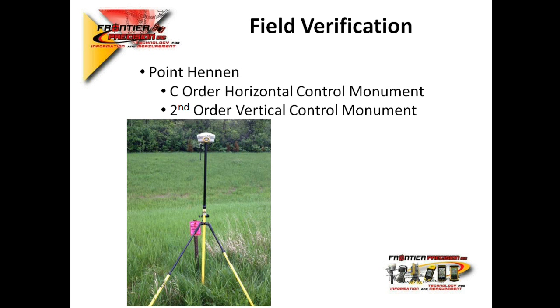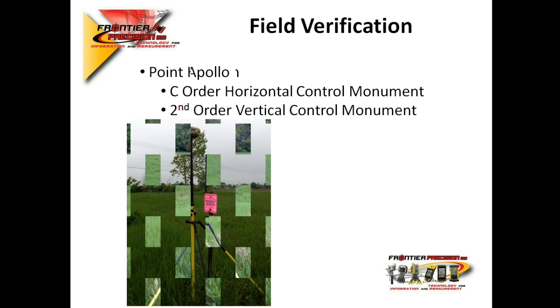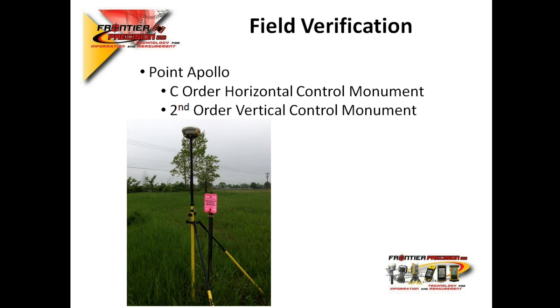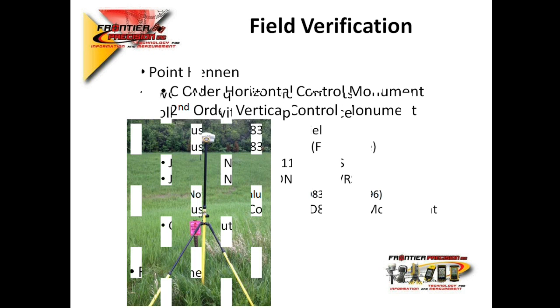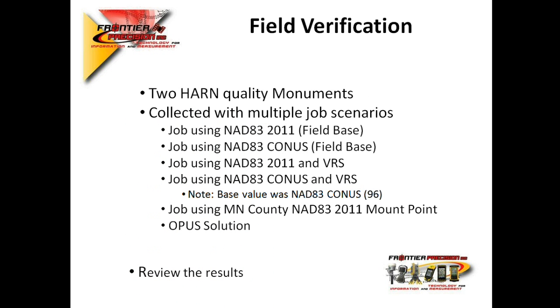You can see that we used a stable bipod setup for our RTK observations. Point Apollo is the only point that we did an Opus solution on. We collected that for about 2.5 hours, and we used a standard tripod tribrach setup for that. So these were the scenarios.